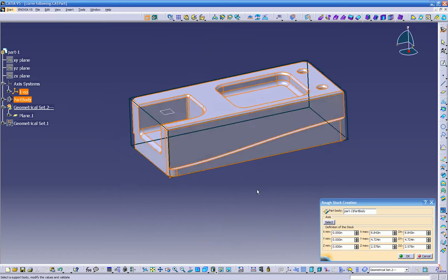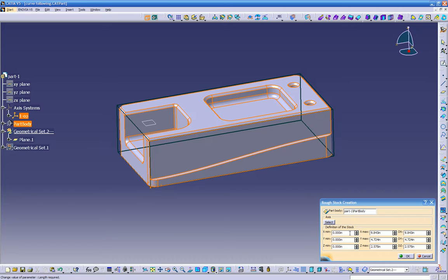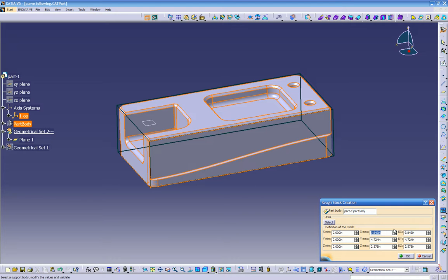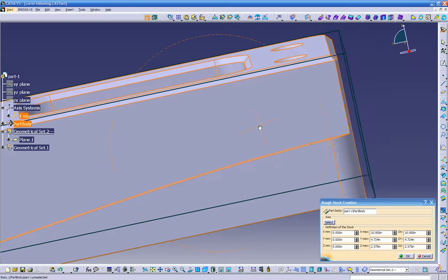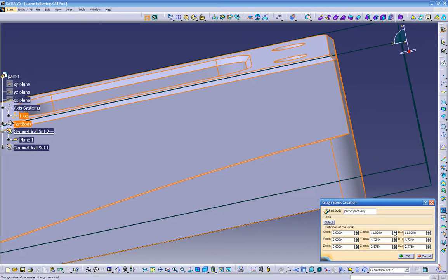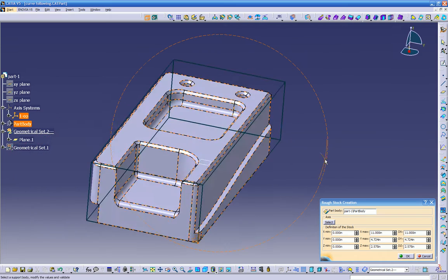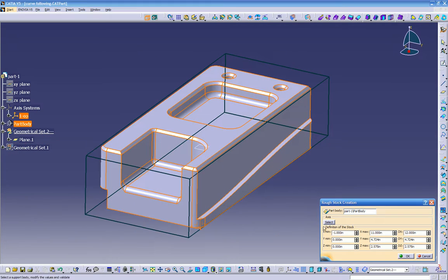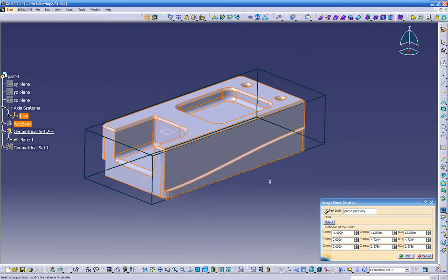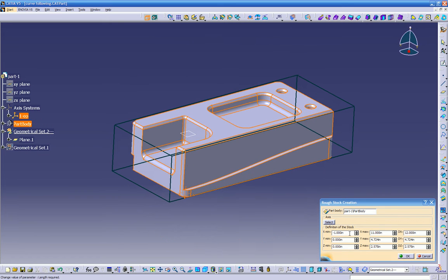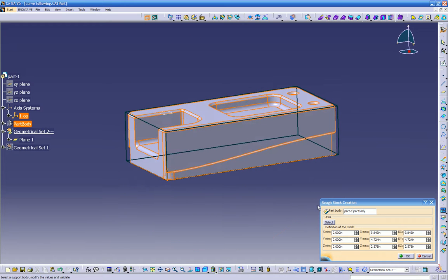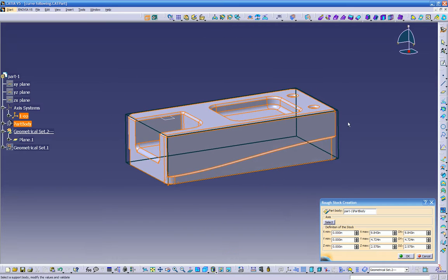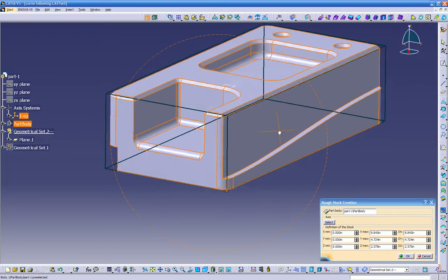But if the stock is bigger in real life, you can come back in here and change it. So right now it's 9 inches. For example, if your stock is 10 inches, you just type 10, and see, automatically it's increasing your stock. See the difference right here? It's making it bigger. You can see you have a couple options you can choose from, and also over here. And once you get the desired material, then you can click OK, and you're ready to go. So right now I just click back on part, and automatically this went back to the standard dimensions.